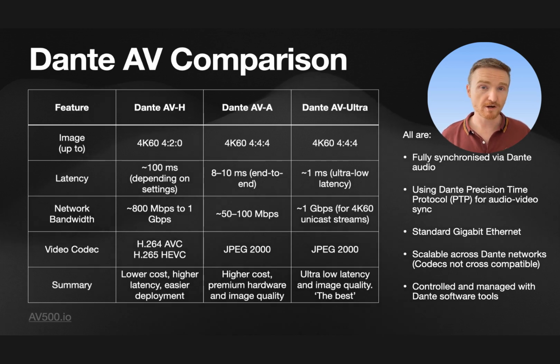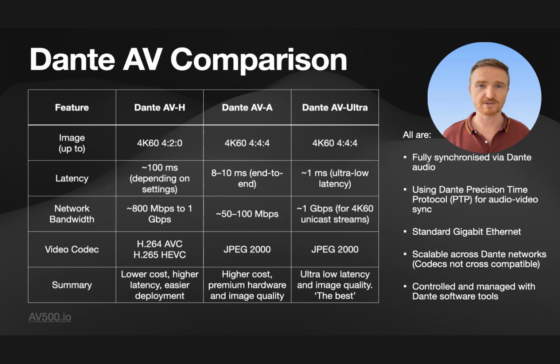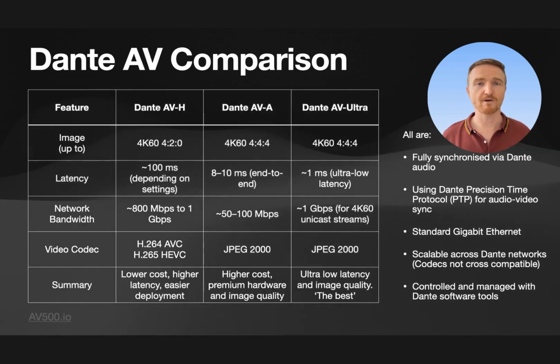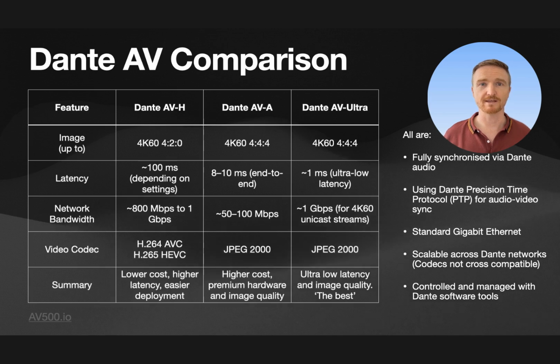Keep in mind you have a lot of different options as far as video over IP platforms. For instance, you have Crestron's MVX system, which provides a really aggressive performance to price ratio. However, it is stuck within the confines of its own ecosystem. NDI is seeing quite a large uptake as far as being embedded into a lot of endpoints like cameras. And then you have SDVoE, software defined video over Ethernet, which is actually like an alliance, an industry group that has many different companies inputting into it, and that is trying to champion interoperability inside of the industry. So a lot of things to consider.